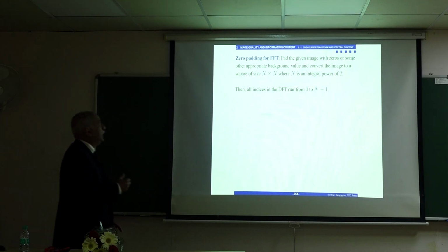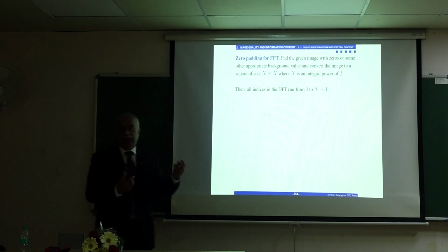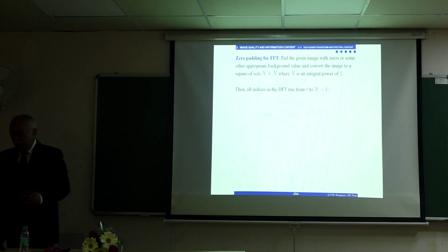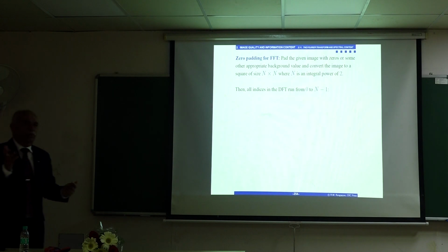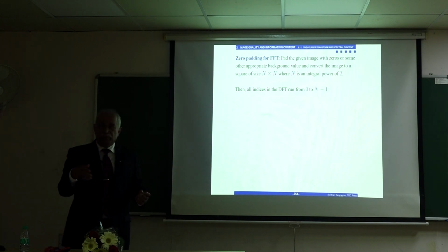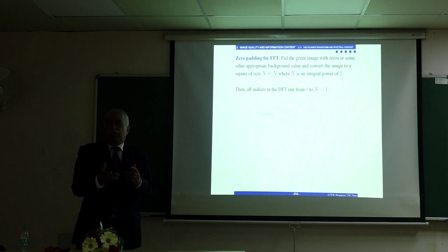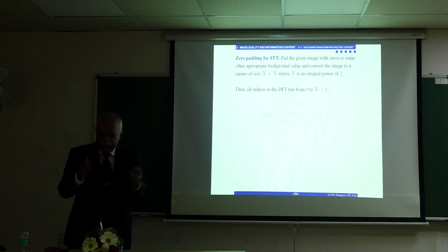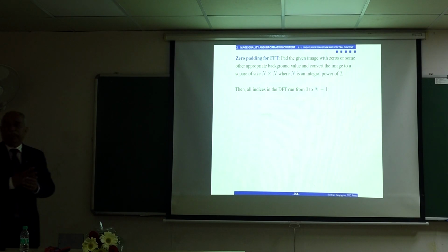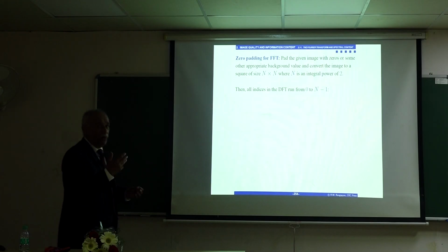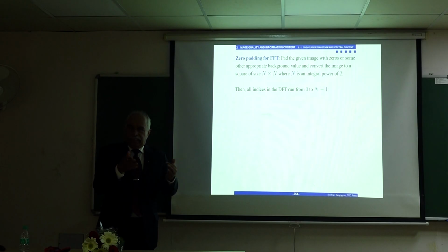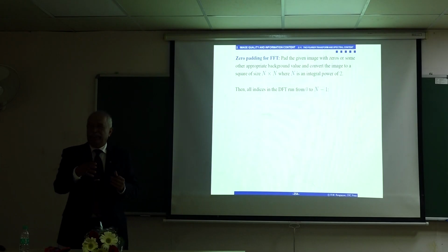When you compute the DFT using the FFT, the fast Fourier transform algorithms, nowadays in MATLAB you can give any number of samples and you get the FFT or the DFT computed using that many samples. But if you want faster computation, depending upon how you compute, it may be advantageous to use a power of 2. That advantage is not much now.